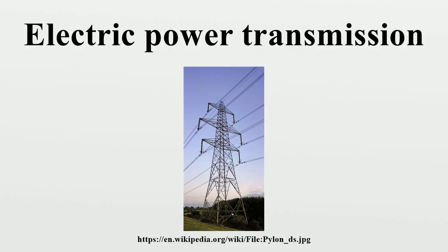Rotary converters and later mercury arc valves and other rectifier equipment allowed DC to be provided where needed. Generating stations and loads using different frequencies could be interconnected using rotary converters. By using common generating plants for every type of load, important economies of scale were achieved. Lower overall capital investment was required. Load factor on each plant was increased, allowing for higher efficiency, a lower cost for the consumer, and increased overall use of electric power.